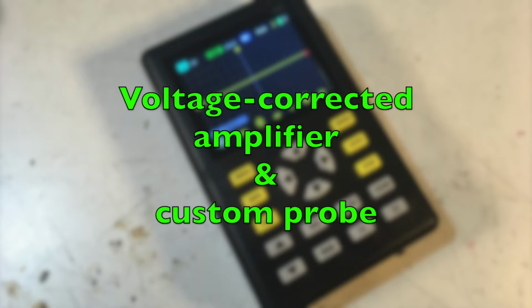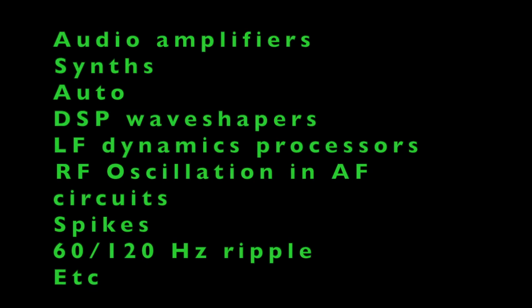So we'll see. Obviously, they had a different intent in mind than I did when purchasing this. But there's still a million uses for something like this. If you're designing audio amplifiers or synthesizers, if you're doing automotive stuff and you need a higher bandwidth floating battery-powered rechargeable scope, it's good for that. If you're programming DSP wave shapers or low-frequency dynamics processors, if you're looking at lower RF oscillation and audio frequency circuits, it's fine for that. If you're just looking for spikes, or if you're measuring ripple at 60 or 120 hertz, as in a regular full wave rectified signal right off the AC mains frequency, then it's fine for that as long as the amplitude is high enough that it's considerable.